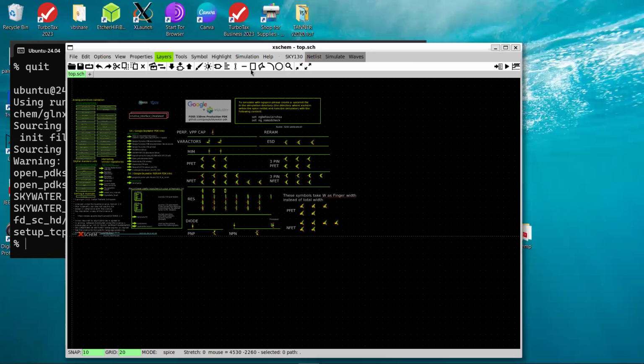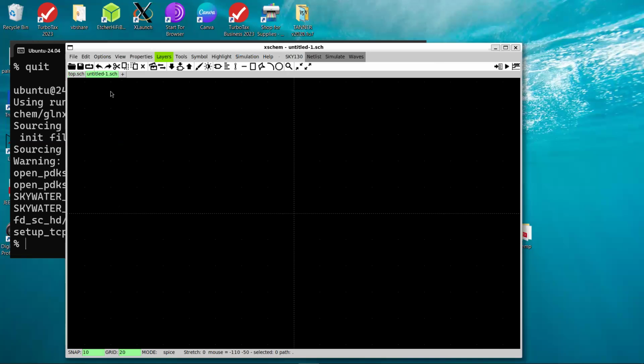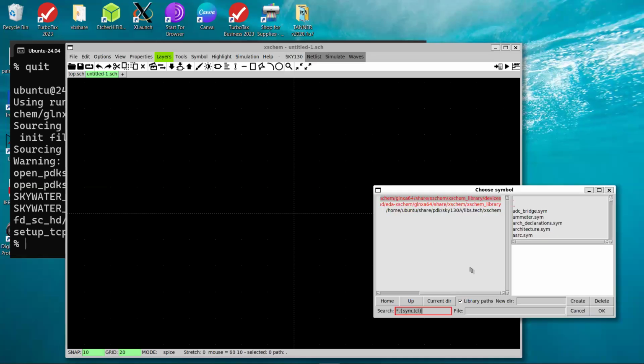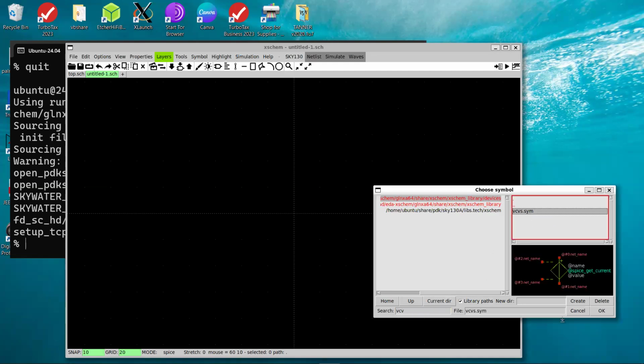Okay, so we're going to create that OpAmp model. I'll just do it in parallel. You guys can start doing it and follow me, or be ahead of me, which is probably better. All right, so start a schematic, and then the first thing you do is bring in the VCVS, just like you did before.